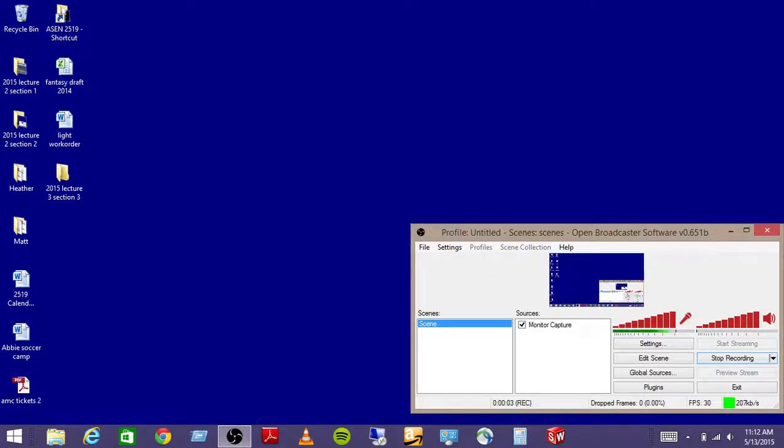Rapid prototype, the Lego model that you should have turned in from homework 3, uploaded to D2L already. So you're going to actually go and rapid prototype this thing. But you're not going to do it. Since there's 17 of us, I'm going to give him all the files, and he's going to print it all on one tray. So it's not one by one. It's more efficient. So what you need to do is upload what kind of file will that 3D rapid prototyper take? STL. So you need to upload an STL file to D2L by